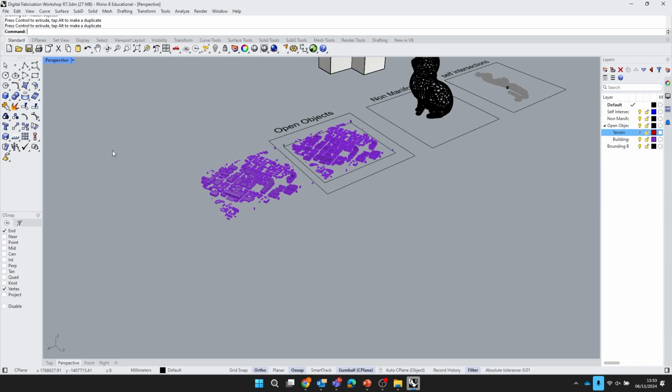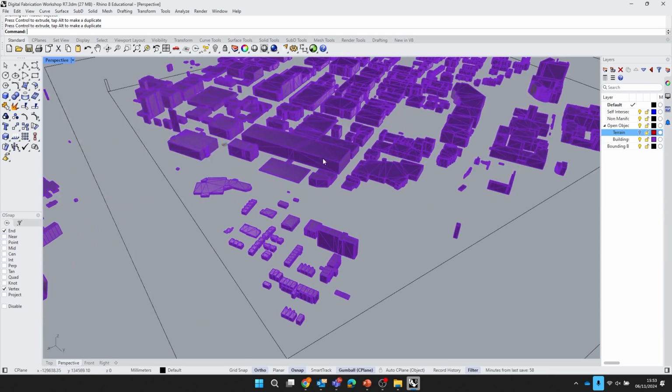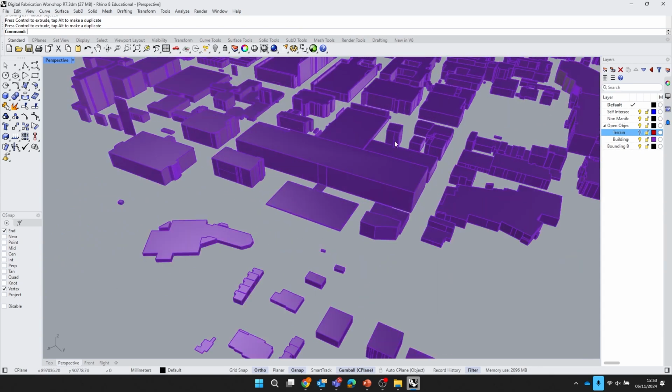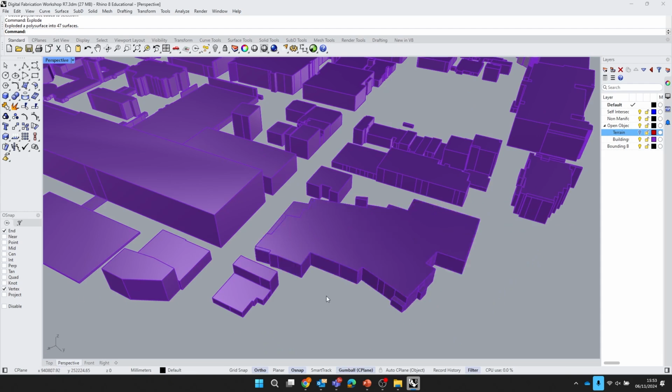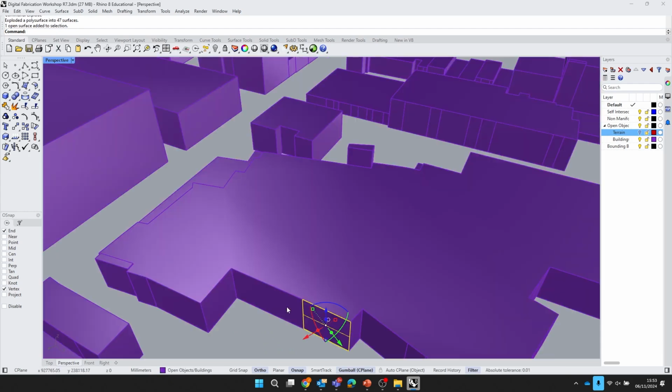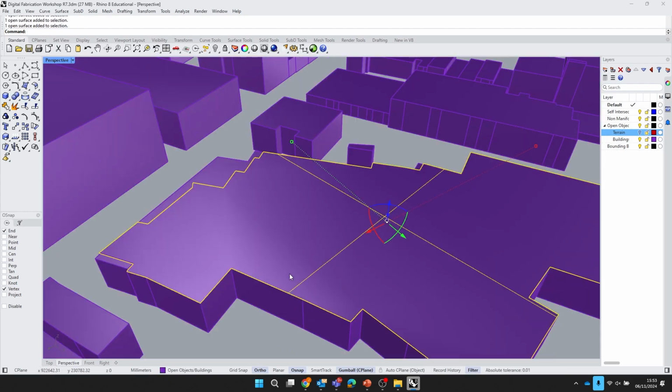The most common laser cut models you would be making are either going to be exploded models. So for instance, now we've cleaned these up, I could simply explode these, just type in explode. That gets these into single faces that I could then just lay flat and laser cut those outlines. Just do a make 2D once you've laid them flat. That gets you all of the outlines, lay them out on a sheet, that's your laser cut files that you can then merge together.